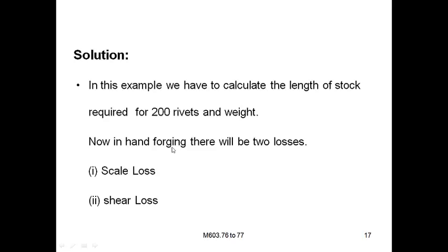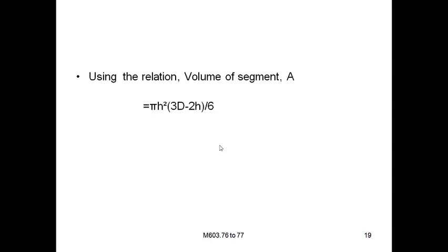Remember that if it is a hand forging or draw forging operation, you have to consider only two losses, those are scale loss and shear loss. The remaining losses you can neglect. So now you come to the problem.